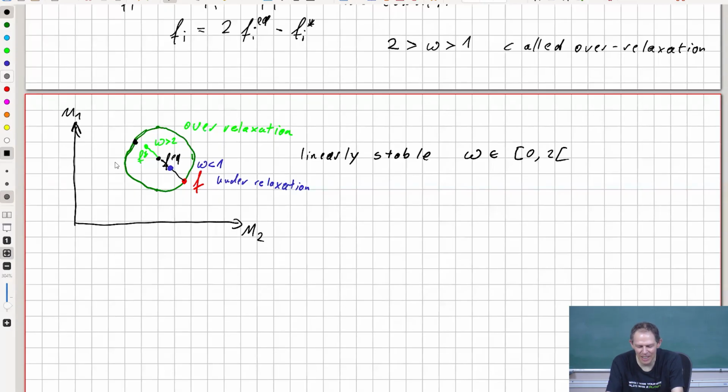Because we are doing lattice Boltzmann and we have done our discretization basically for solving the Navier-Stokes equation, if you were hoping that under relaxation gives you more kinetic effects, then unfortunately not, because we have used too few speeds.